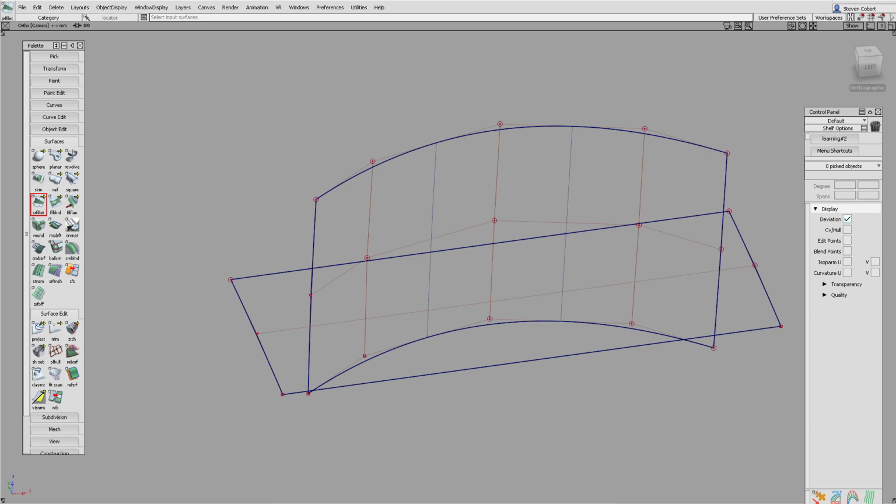Now we're going to look at how we can achieve the best quality fillets. In other words, how we can get the most accurate but simplest results. We're going to look at the factors that affect this by looking at the surface fillet again. Here we have a degree 2, 3-span surface intersecting another simple surface. I've deliberately chosen a low degree multi-span surface to illustrate a point. We would not usually want a degree 2 multi-span surface for A-class work because the continuity at the knot lines will only be G1, 1 less than the degree.